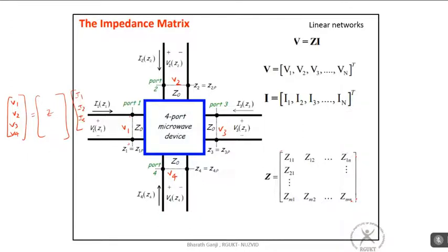If you ask me what is the port current or the port voltage at this location, on these lines, because we are dealing with scenarios at microwave frequencies, the voltages and currents are basically waves. So defining a port location is a very important thing, because the location at which you define the port might change the matrix, or might change the behavior of the network.